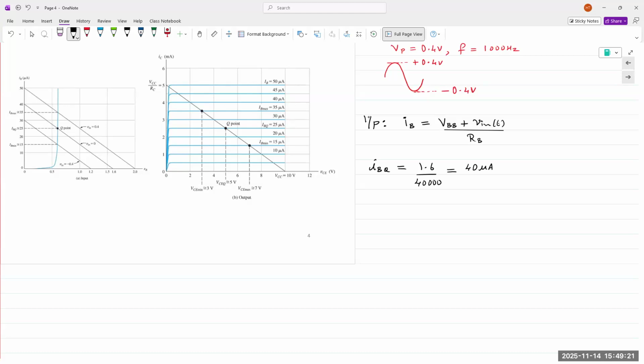It's an amplifier. So before we apply the AC input, we apply the DC biasing voltages. When we apply the DC biasing voltages, our Q point is fixed in the active region. When it's fixed in the active region, it has a current value and a voltage value. So on the input side, it is VBE and it is IB.